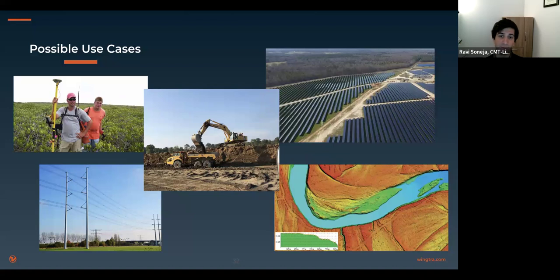We did notice, for the most part, it looked good, but there were some spans where the static wire did not come through completely. I'm not quite sure what's going on there. We're going to probably try to find another set of transmission wires and fly them again at about a 60-meter AGL with the proper side offset left and right of that center line to see what we can determine about whether or not it's usable for that. But if you're flying this on a multi-rotor application, yeah, as long as you fly at the correct AGL, you can pick up those features.